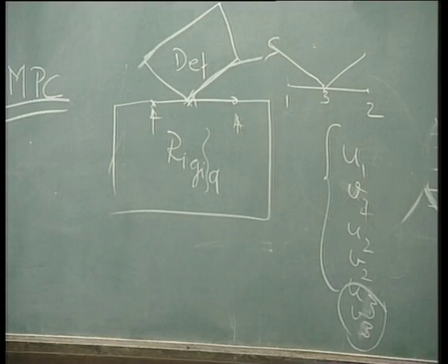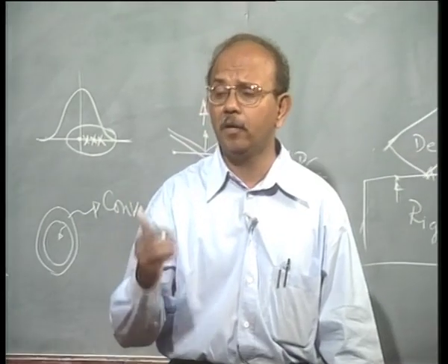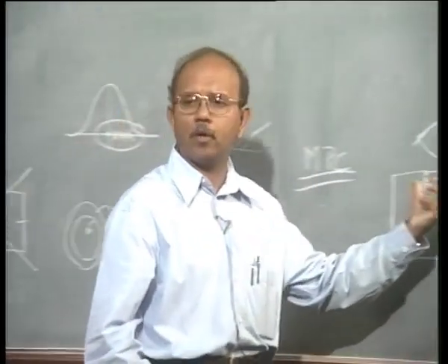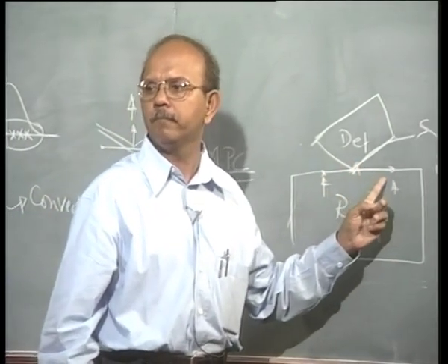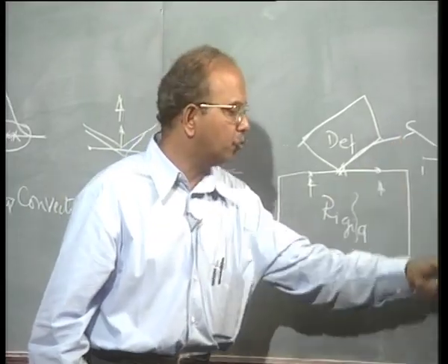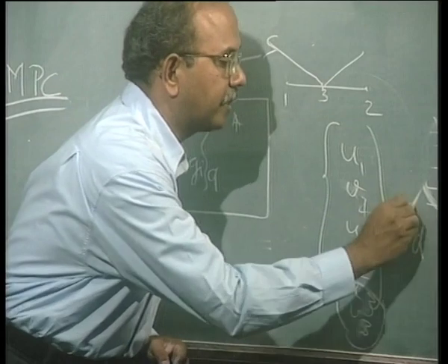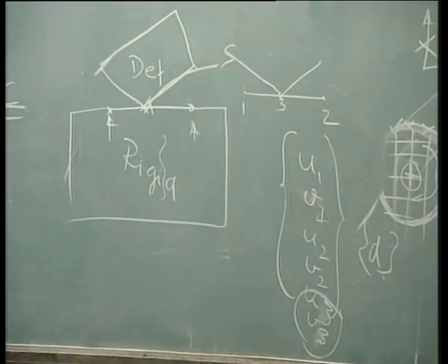So a contact element consists of 3 nodes, but they are not separately defined nodes. Note this carefully, they belong to the two bodies. 2 of them belong to the master body, and 1 belongs to the slave body. If you put them together, you will see the D vector which we usually write as U1, V1, U2, V2, U3, V3, U4, V4.